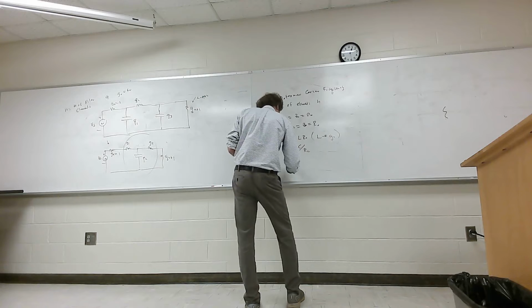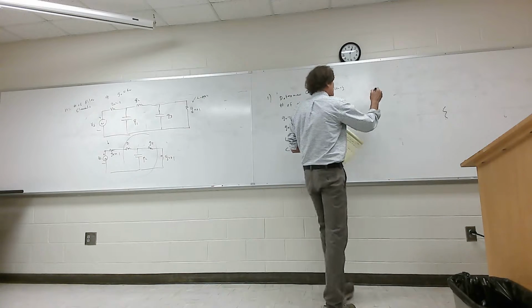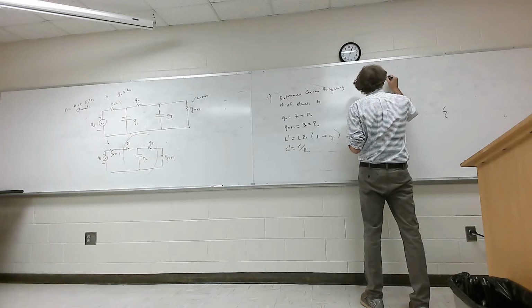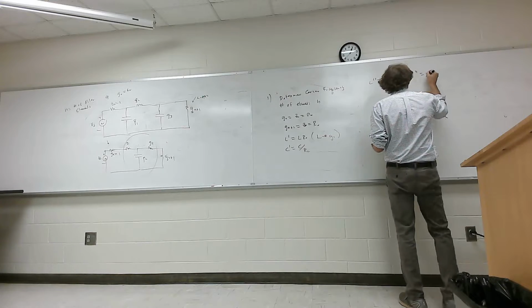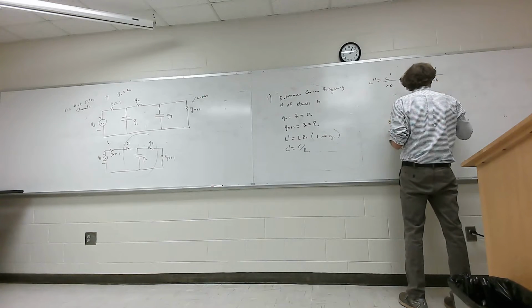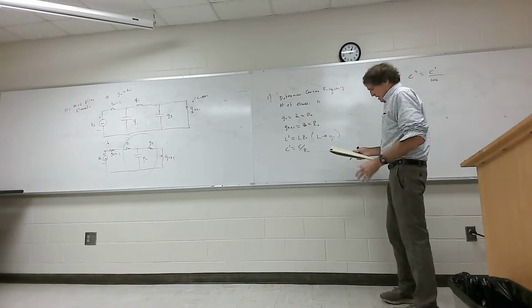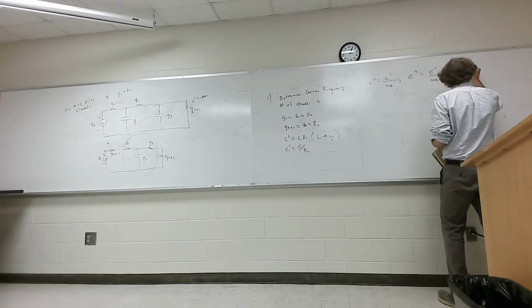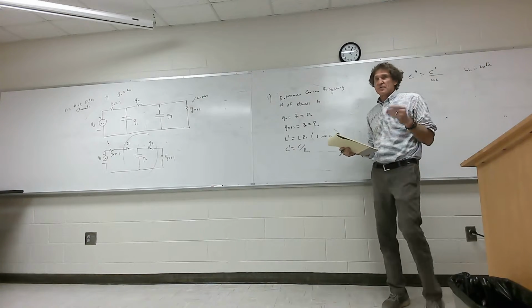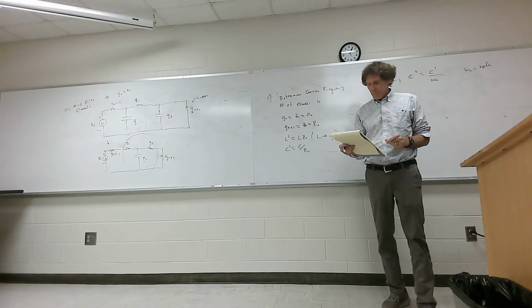And then finally you get the final values, and these are the ones you care about. You're going to get L double prime equal to L prime over omega C, and you get C double prime equal to C prime over omega C. And omega C is just 2 pi times the corner frequency, whatever that is. It's the frequency you want the filter to start acting as a filter, or the beginnings.